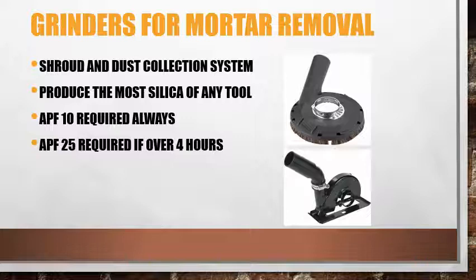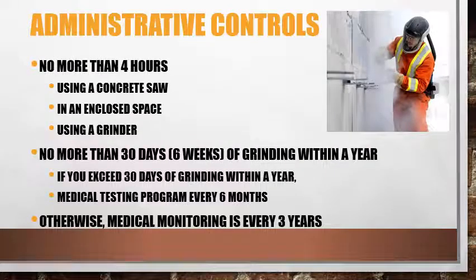If you are using a grinder for mortar removal over 4 hours, then you need an APF25 respirator. This is what an APF25 respirator looks like. And something we can do as your employer to help protect you from silica dust is to have you not be using these tools more than 4 hours consecutively in a shift.